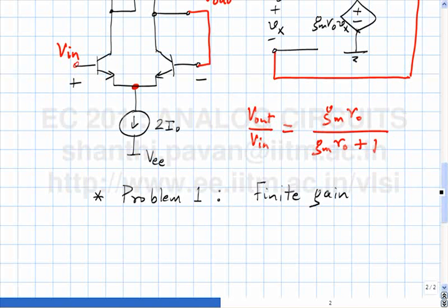So if the gain of the op-amp becomes larger and larger, you can realize a larger closed loop gain, because you can make f smaller. 1 over the feedback factor is the closed loop gain, but if you make f small, the loop gain, which is A times f, becomes small, which causes AF by AF plus 1 to deviate from unity. One clear thing to do is we must increase the gain from what we have, several hundreds, to maybe 10,000 or 100,000.